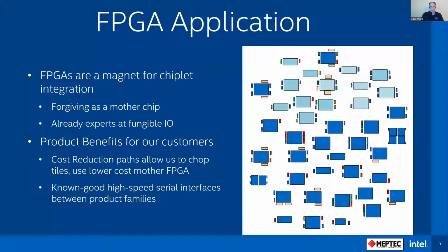We focused on the tiles within Intel and PSG. We were already experts at fungible I/O, a fungible real-time I/O where you can address different standards with the same silicon, which was a pretty common FPGA application. And the I/O scale differently with the processes, so it made a lot of sense to break those off into separate tiles.